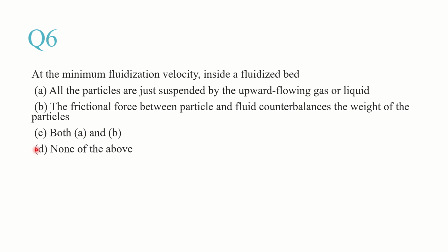We know that at the condition of minimum fluidization, the particles are suspended in the fluid medium when the fluid is passing upward, as in upward flowing gas or liquid. So option A is true. Option B says the frictional force between the particle and the fluid counterbalances the weight of the particle. This is also true, right?